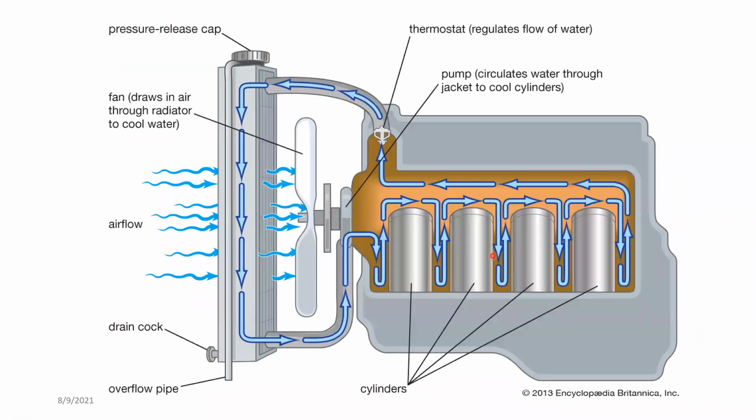The whole system we can show like this, as you already know about these things. I'll start from the bottom of the heat exchanger or radiator here. We have the coolant, the cold water. This comes through the water pump. So this is the pump, right? This system uses a pump, though it can also operate without a pump, which I'll explain a bit later. The water comes through the rubber hose here, then comes up to the pump. From the pump, it's pressurized and pumped into the hose, recirculated to the engine block.